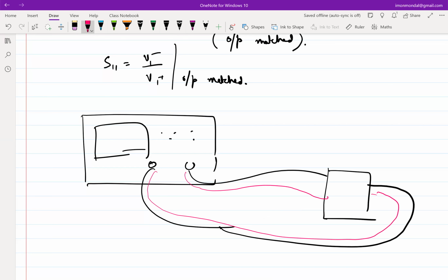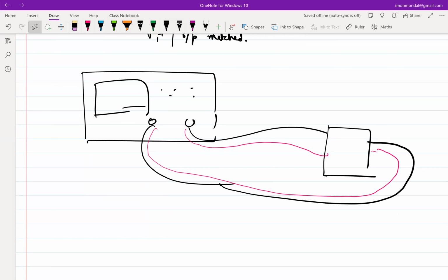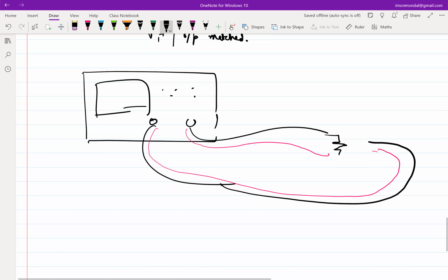So you have these big long cables, and let's say you want to characterize this 2 port, and let's say I want to characterize only one resistor, just a resistor. Find out the impedance of the resistor using this S parameter analysis. So what does this 2 port? I mean, then I don't need the second port essentially, right? So all I can say is that it's a 1 port analysis. I can say that I want to find out the impedance of this RL.